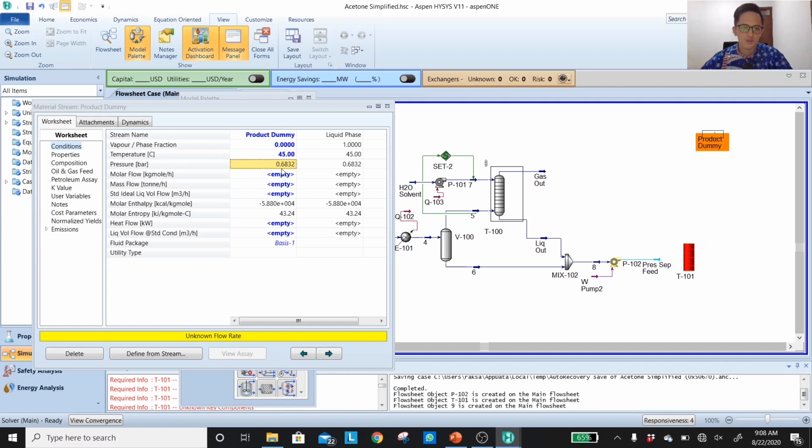And once you do that, you will realize that the bubble pressure for those conditions would be around 0.68 bar. And this is not really a good number because it's already in a vacuum condition. In a vacuum condition, it's going to be costly and hard to control. We have to install an ejector or a vacuum pump. So again, this is, I think, quite similar to the second distillation in the DME case, where we will compromise or we will check other options.